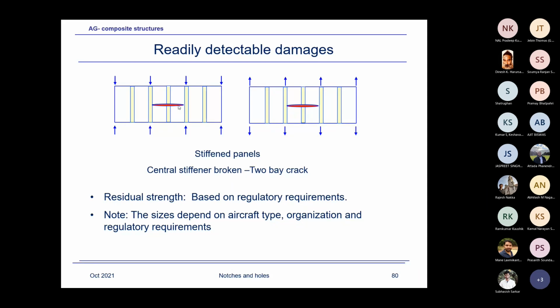Their toughness is different, one higher, one lower. Unfortunately, the material which has a higher toughness has a lower modulus. Toughness increase reduces the shear modulus capability of the matrix. So as a result, the compressive strength with the open hole, like a quarter-inch hole, for the material which is brittle is higher than the compressive strength for the material which is ductile.